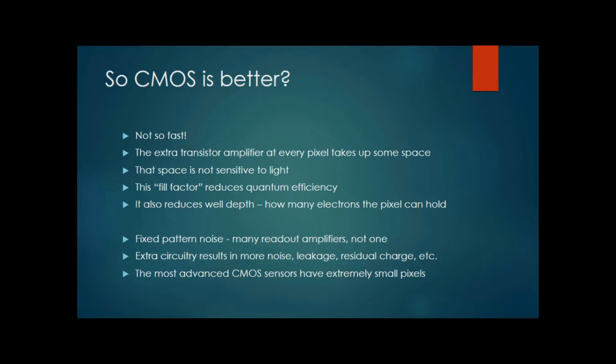So there's also extra circuitry in there. There's amplifiers, ADC converters, and things, and these do make electrical noise, and this can degrade the performance of the sensor. One thing you often notice on CCDs is the readout amplifier in the corner makes a little bit of light, because every silicon junction is actually a diode which generates light like an LED does, a light emitting diode. All transistors do this, and the more you have, the more of this light is emitted. So some care has to be taken to make sure that light doesn't contaminate your image even as you're reading it.